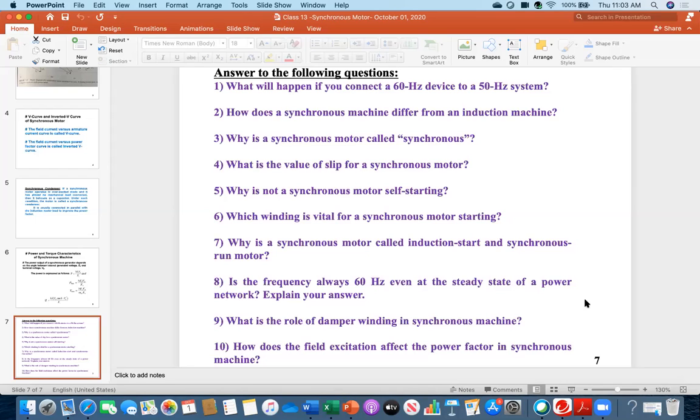But inside the stator of the single phase motor inside the ceiling fan, you need a capacitor, which we did not study in the case of the three phase induction motor. We studied that you need a parallel capacitor to improve the power factor. That is a different thing.